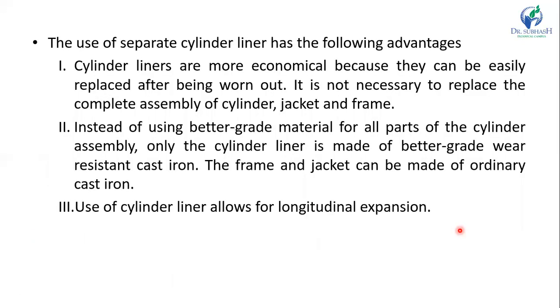The use of a separate cylinder liner has different advantages. What are the advantages? The cylinder liners are more economical because they can be easily replaced after being worn out. It is not necessary to replace the complete assembly of cylinder, jacket and frame.